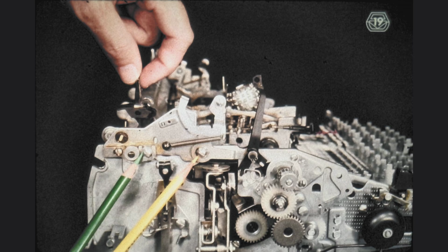It is important to mention that printing deficiencies can best be checked if the ribbon being used is an old fabric ribbon. Furthermore, we must always be aware that the adjustment of platen height cannot be finalized without previously adjusting the alignment and character selection mechanisms. The routine is to approximate the position of the platen so that the character selection mechanism can be tested. After the alignment and character selection mechanisms have been properly adjusted, then it is possible to finalize the platen position